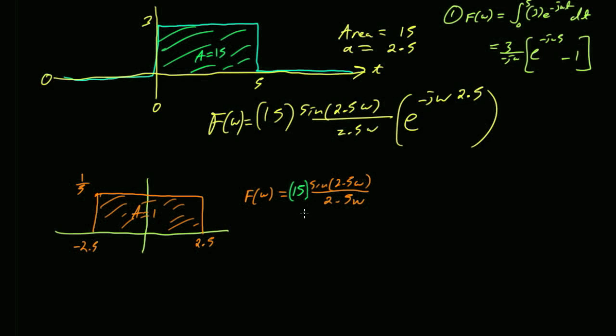Okay. So now that expression is the Fourier transform for that function. And now I got to shift it to the right in order to get the one that was my original question. How do I do that? Right, so we've learned that when you take your original signal and shift it to the, see here we go with the minus signs again. When we shift it to the right, when we shift it by tau units, that equivalency in frequency space is to take your original Fourier transform and to multiply it by e to the j omega tau. Right. In this case, I want to take this and shift it to the right. That's a shift. So a shift to the right means you want to have tau minus 2.5.